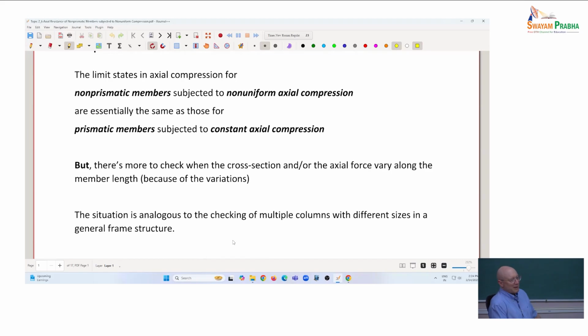What I want you to imagine is, suppose we want to do a column strength check on columns in some structure. Sketch whatever structure you wish. I've got a whole bunch of columns, I've got all these loads, and I'm going to do an eigenvalue buckling analysis on this group of columns.